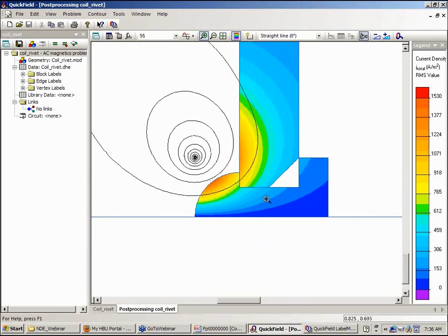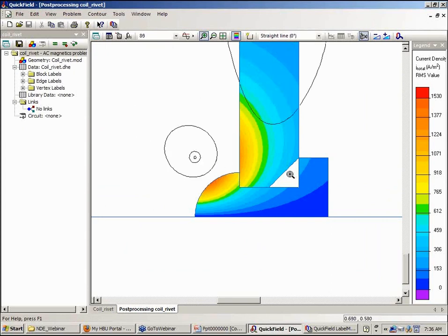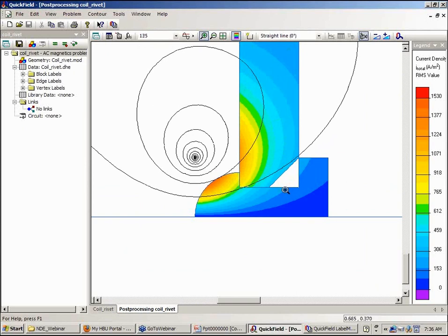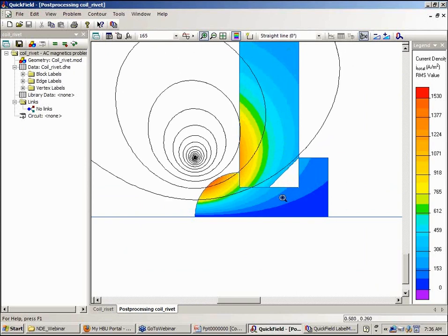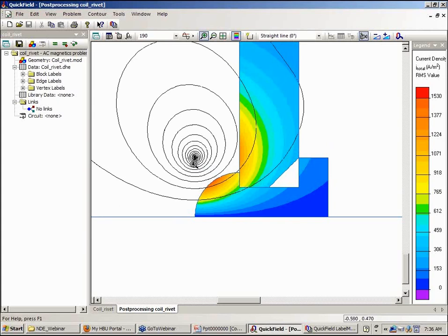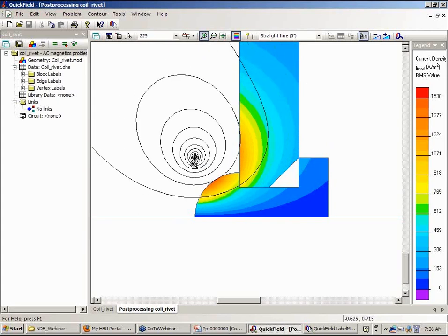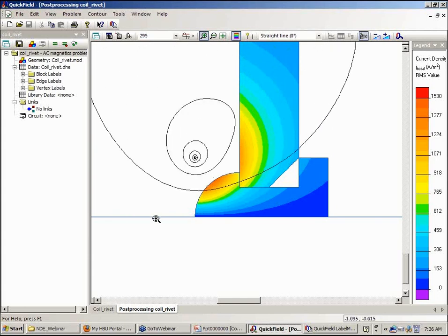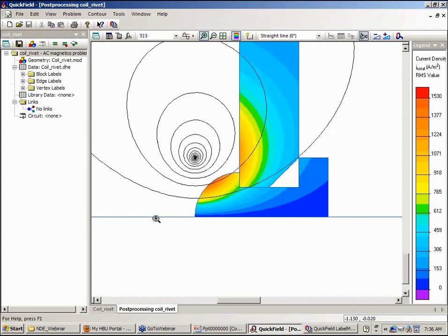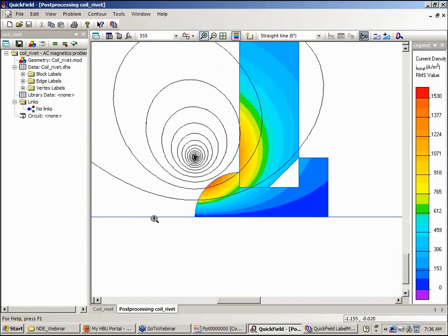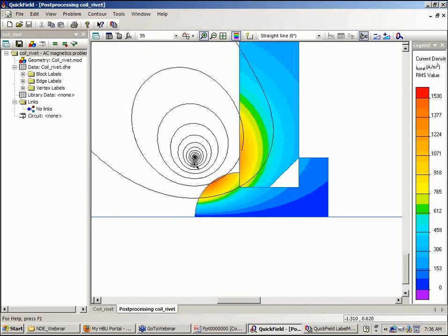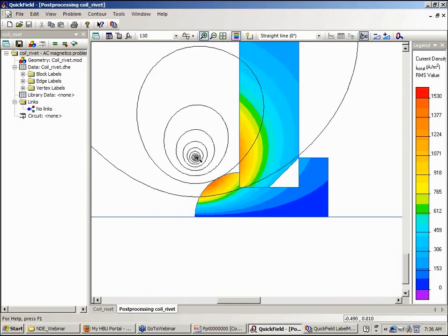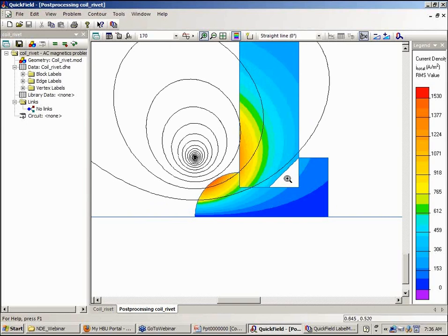There's no eddy current that's flowing in the corrosion pit since it has zero conductivity, the same as air. Now I could sweep the frequency of the excitation coil like we did before and monitor the change in magnetic field as a function of frequency or coil liftoff or coil geometry, and design a coil that is best suited for detecting these types of defects.